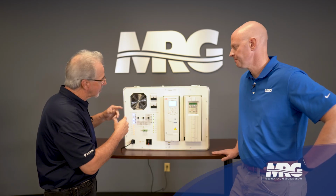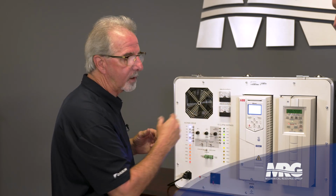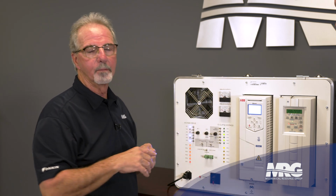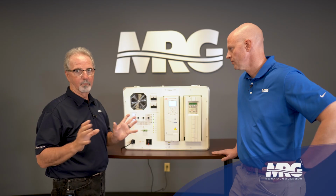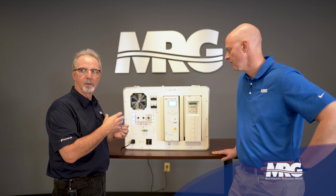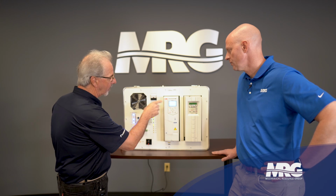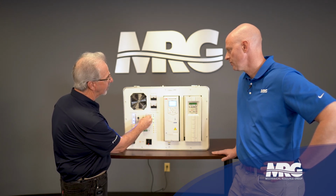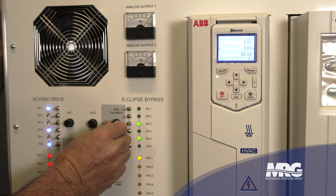Gotcha. Okay, so we have pressure transducers in there, and we have a set point. Just for conversation's sake, I have a set point of 9.7 inches of water column, extremely high for stairwell pressurization, but I wanted it to be there so we can demonstrate and you can see bigger numbers. So I'm at 9.7. Now this is my feedback coming to me. As I begin to lower my feedback, you'll notice my output frequency begins to speed up.